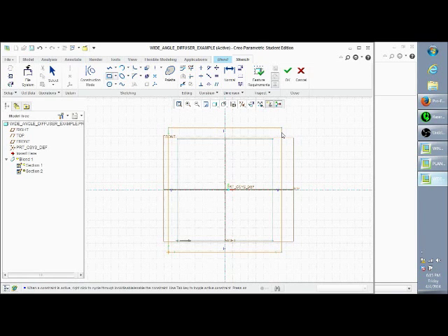If you are creating a shape and you want it to be a little bit offset, say you want it to look kind of like this, so it'll go from the big box to the small box, then you don't want it symmetrical about this top line. But we want it to be symmetrical about both lines because we want these reference datums to be in the middle for both of our shapes, because it makes it easier for references, like for this sketch. So go ahead and left click to set it, and then notice my tool is still active. You want to middle click to exit out of that.